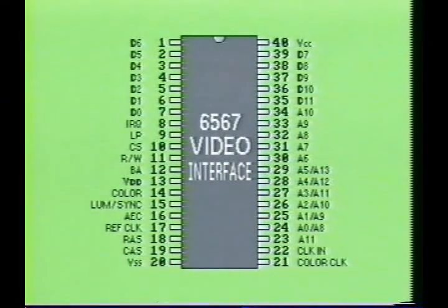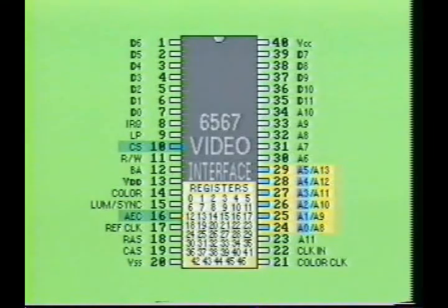Addressing of the video interface by the CPU occurs when the address enable control pin is normally high and the chip select pin is low. This sets up bits A0 through A5 of pins 24 to 29 to be used for addressing all 47 of the chip's internal registers. Since there are only 47 internal registers in the device and 64 possible addressing combinations which can be present on pins 24 to 29, various combinations of internal registers can be addressed at one time, thus merging all corresponding register bits together to form one basic input or output.